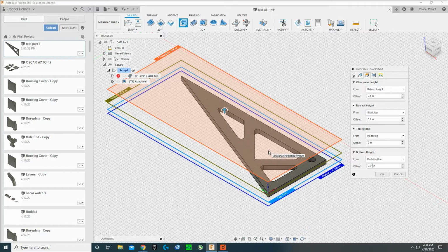With a drill hole, you can get the same size drill bit in there and go back in by hand and drill it out. With the huge pocket, if you have a layer of aluminum still left over, there's not much you can do about it. So you really want to make sure you're giving yourself that extra bit of error and putting in that 100th of an inch below the bottom of the model. So that's all set.